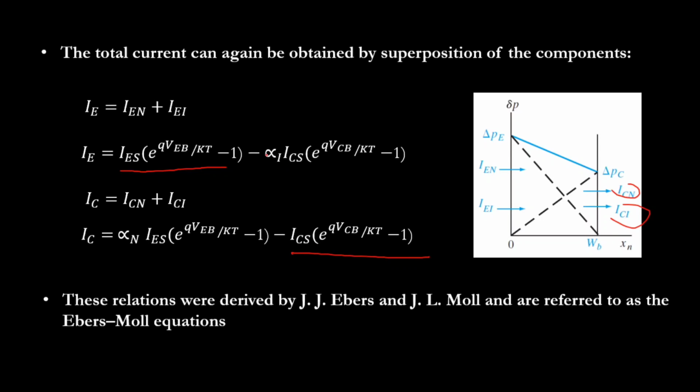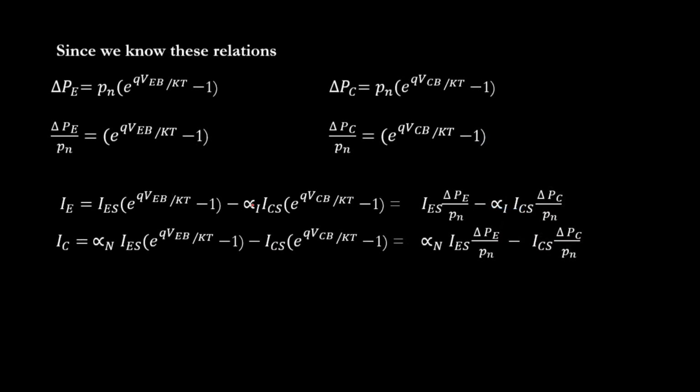So this I can represent using a diode exactly. This is actually the current. So these two things I am supposed to represent using a current source. This is a current, alpha into ICS is IE, alpha into IES is equal to IC. Right, so I need to represent these using current sources, and these two I need to represent using a diode. For that, slight changes we need to make.